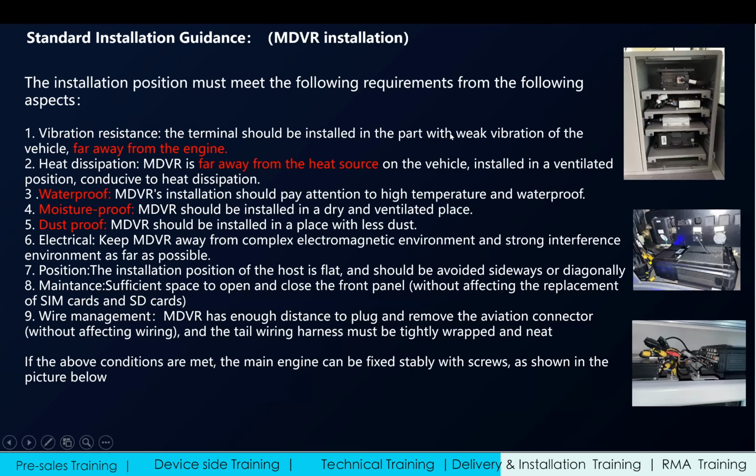Next is the MDVR installation, which is the most important part of the whole installation. For our standard MDVR installation, the following 9 points are required. The first one is that the location of the MDVR installation should be far away from vibrating parts, like the engine and the wheel, these kinds of shaking parts, because the vibration will impact or damage the hard disk in the MDVR.